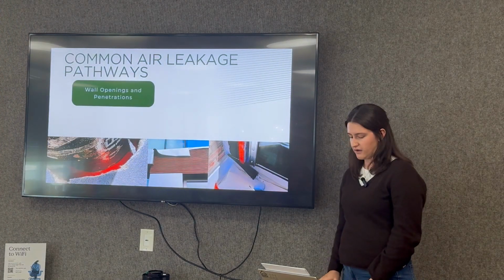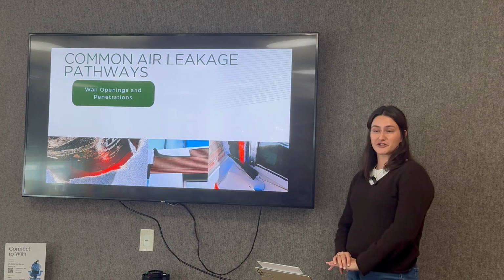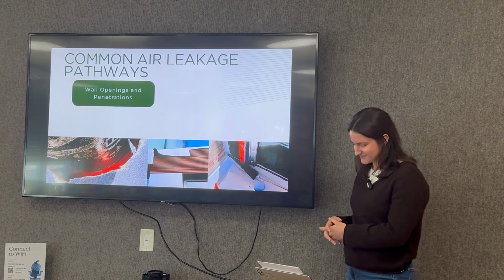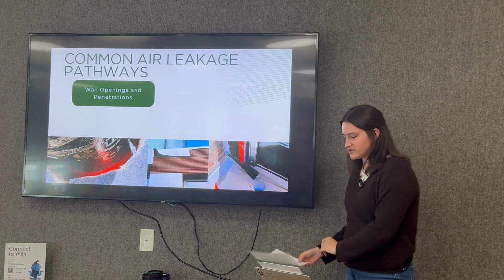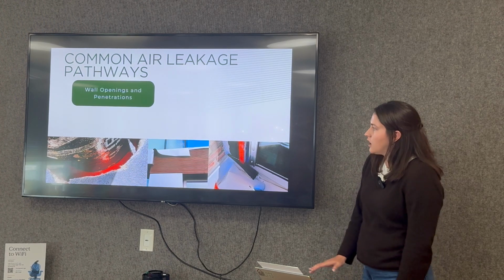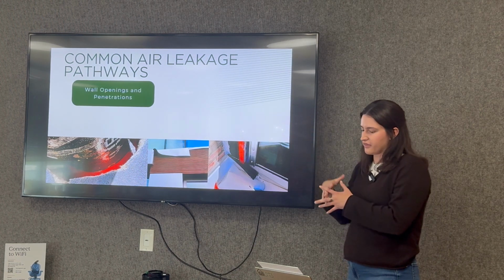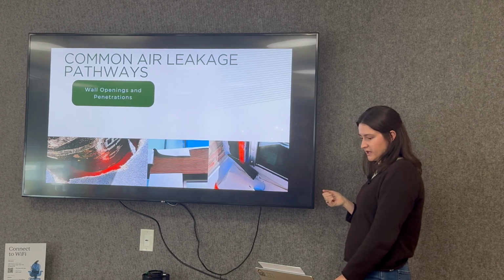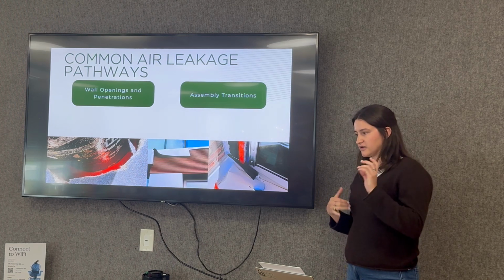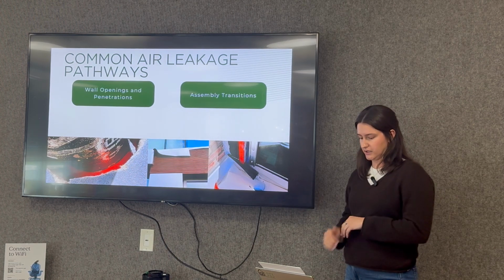So knowing the risks of non-airtight buildings, where do we typically see air leakage? It's no secret that construction deficiencies typically happen where multiple trades come together, right? So the sentiment is typically the same for air sealing. We'll start with wall openings and penetrations, like any through wall or through roof penetrations, like this pipe penetration there, the perimeter of that's not sealed, so that's an air leakage path. And at window and door openings, transitions between adjacent wall systems like a roof to wall condition, so parapets, roof edge detailing, and wall to wall transitions like opaque wall to fenestrations.